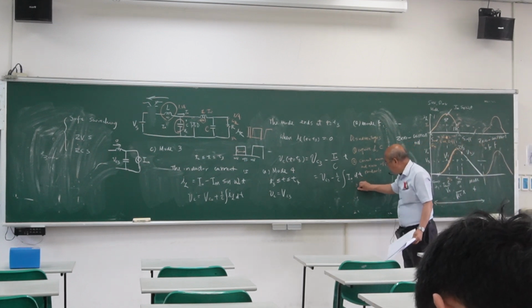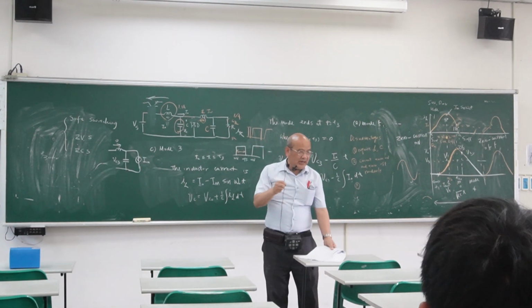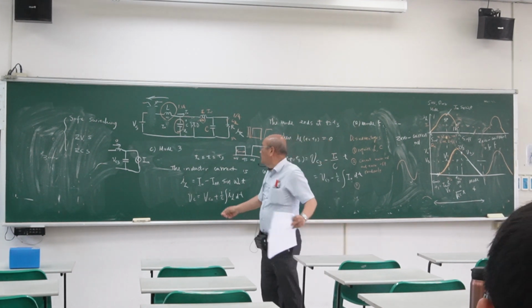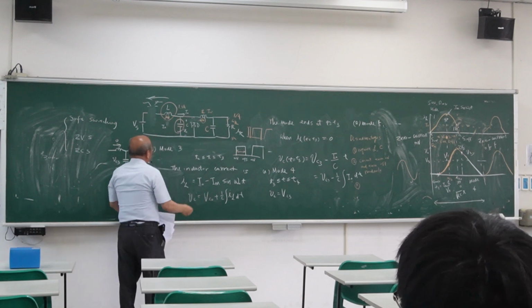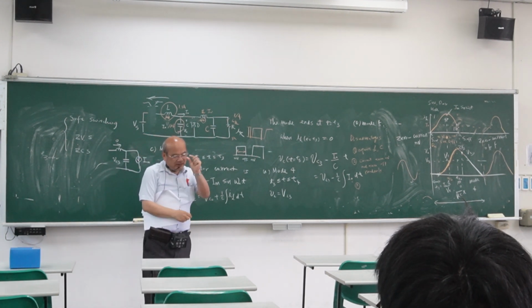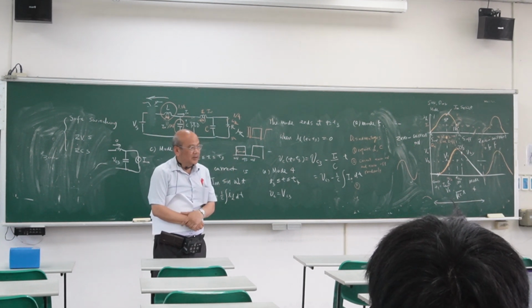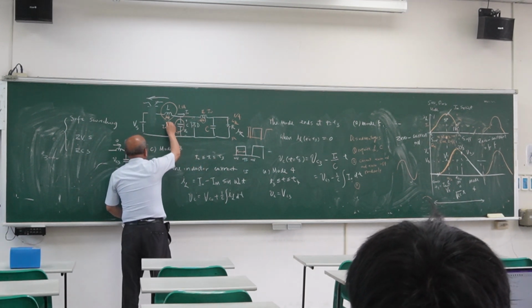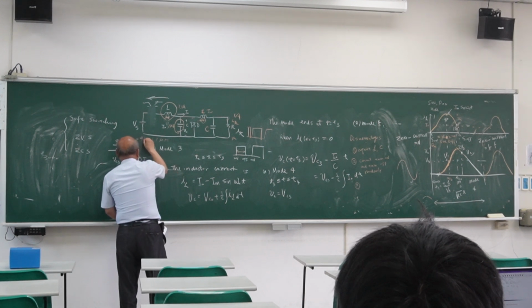How about the third part? What is the LC? Do you think the LC is large L, large C, or small L, small C? Small. So you say, I need 1 microhenry here, I need 1 microfarad here. But can you get precisely 1 microhenry every time? No. For this order, you can get 1.1 microhenry or 0.9 microhenry.